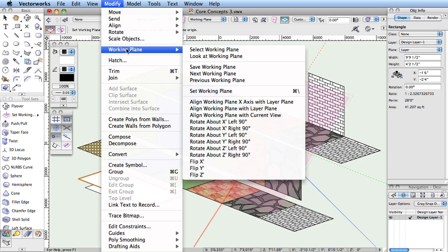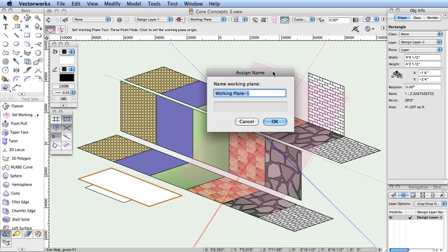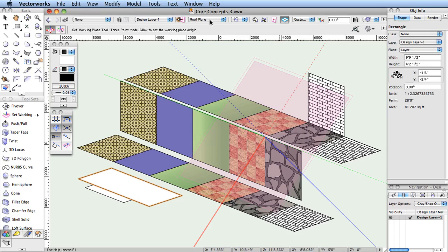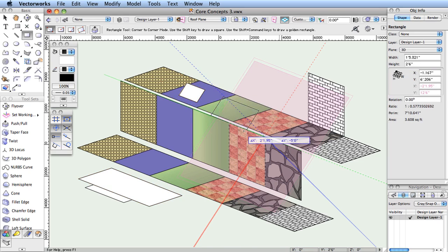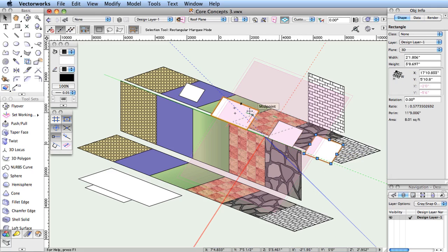Working in 3D requires a plane in space so that clicking on the flat display can be calculated to intersect somewhere before infinity. So, in summary, all editing and creation in 3D space happens in the working plane. The working plane may be aligned with an active layer plane or the ground plane. Snap points of existing 3D objects always override the working plane. Otherwise, all 3D creation, reshaping, and moving operations will be in an active plane.